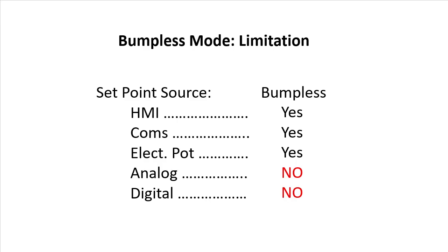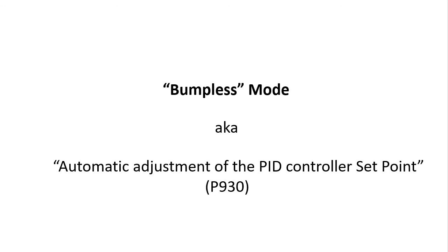And I should point out that I'm using the term bumpless because it's the most common term for this industry. But you won't find the word bumpless in the WEG programming manual. They prefer to call it automatic adjustment of the PID controller set point.